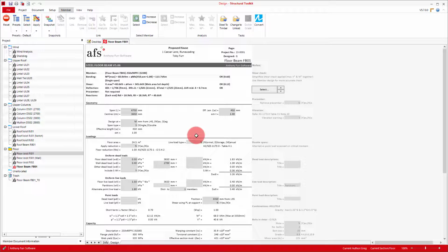It's an extremely important aspect of design to consider, and it isn't captured in our individual designs due to us having simplified the approach down to isolated single span beams. A good approach then might be to limit our total deflection to 15 millimeters, so we'll bump up our beam size to a 300 PFC. With that done, our first floor beam design is complete.